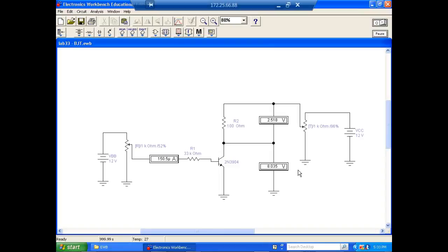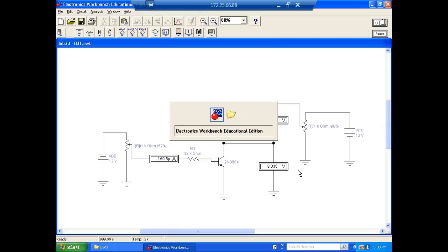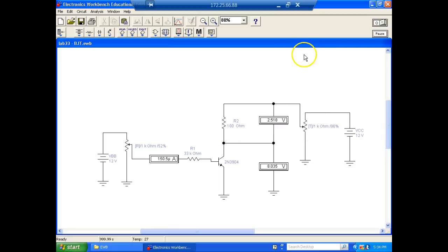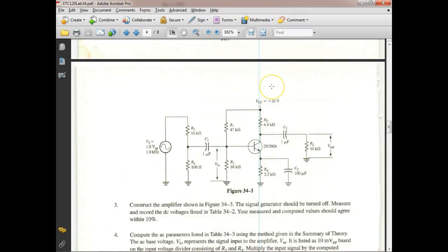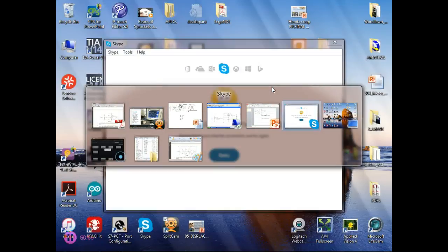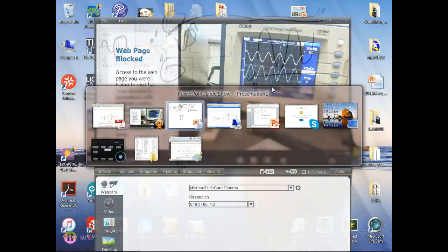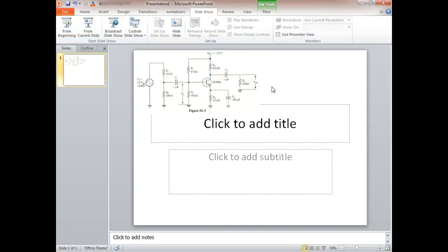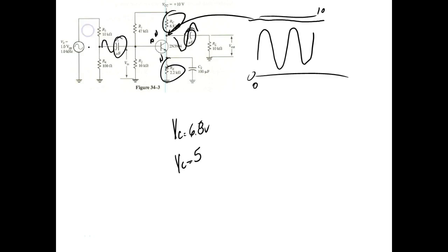No, it's going to be biased, because it doesn't bias through the capacitor, it biases through the resistor. Sorry. Let me go back to my PowerPoint. I just went right past it, and we did it the other night. That's what we did right off the bat: we deliberately did not bypass.